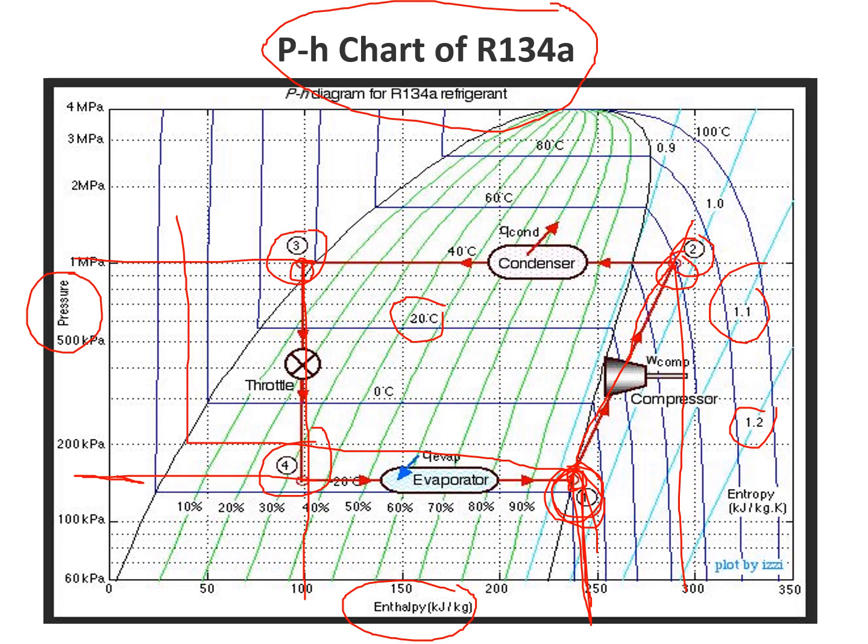In this way we can easily observe the enthalpy at 1, enthalpy at 2, enthalpy of 3 and 4, both are the same. So by knowing the enthalpies, actually we can do the analysis of that particular thermodynamic cycle.